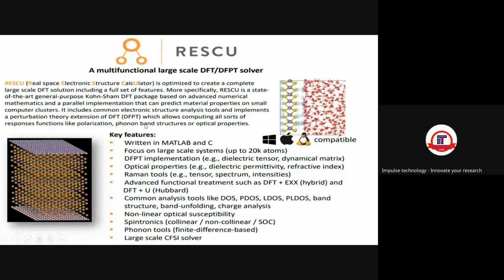If we talk about the key features of this RESCU software, it is written in MATLAB and C language, and it can focus on large scale systems. Up to 20K atoms you can easily simulate with this RESCU software. Also, RESCU comes with a DFPT implementation, so you can calculate the dielectric tensor, dynamical matrix, and optical properties like dielectric permittivity and refractive index.